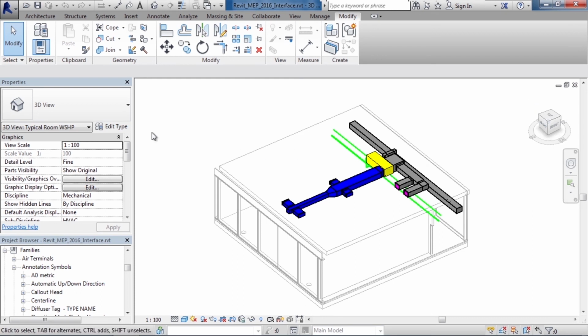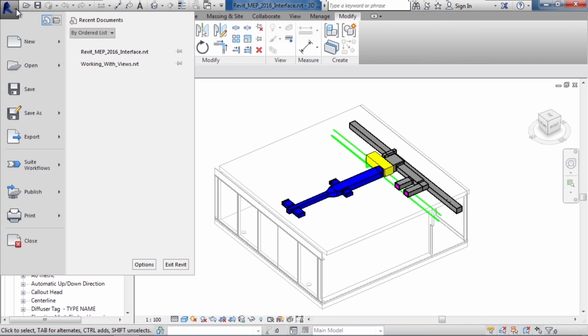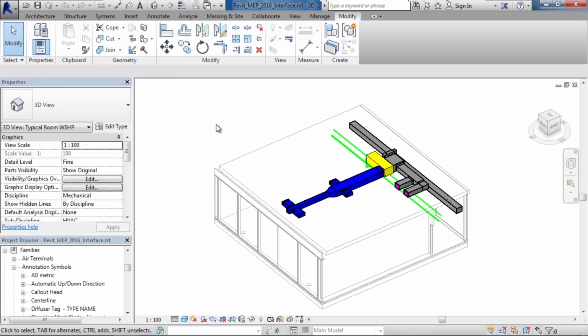The very top of the Revit window on the left is the quick launch bar. This allows us to quickly open, save, undo, redo, and check various settings. The large R in the upper left allows us to do the same thing, but it also contains the Options button, where we can set the various options for Revit MEP. And lastly, the toolbar in the upper right is the Help toolbar, where you can search for help on commands or how-tos, or connect to Autodesk 360.